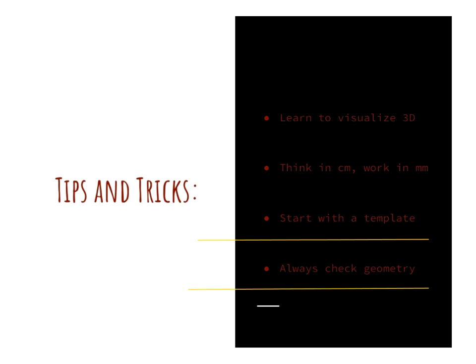What that means is you're always looking to close off your shapes. When you use a program like SketchUp, it's easy to look like you have connected two lines, but actually be off by a millimeter or so. So when you're making your designs in here, you want to make sure that you're snapping onto the corners and closing off all of your faces and your sides.